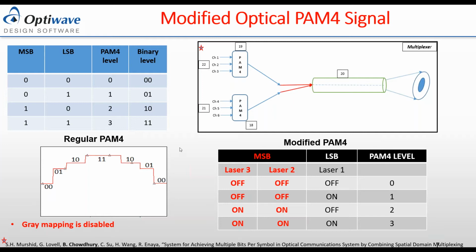My signal to noise ratio is A by 3, because the same laser diode, based on the I of a PAM4 signal, the power is divided into four levels or three different I's. If everything works perfectly, the signal to noise ratio is not A anymore. It is A by 3 if the total power at the beginning was A.